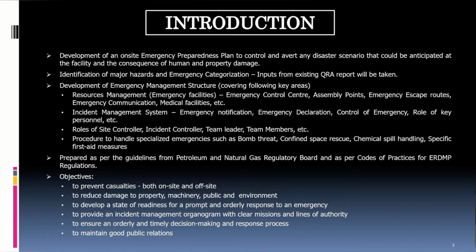For effective response and recovery efforts, an emergency management structure is developed. It includes resources management, that is facilities like emergency control center, escape routes, medical facilities must be available. An incident management system includes emergency notification to the employees, control of emergencies, etc. It clarifies the roles of site controller, incident controller, and other people who play key roles in such emergencies. It also explains the procedures to handle certain emergencies like bomb threat, confined space rescue, chemical spill, and other such